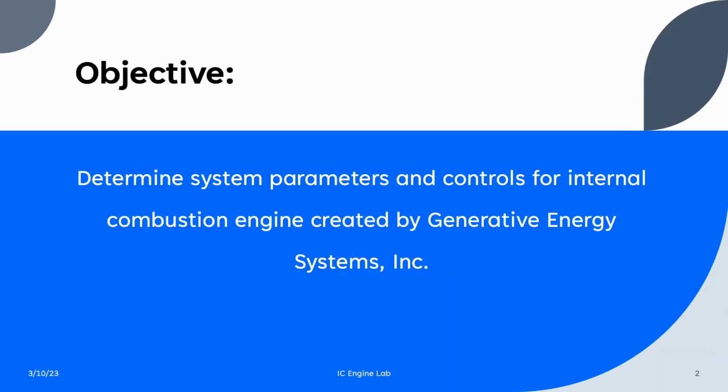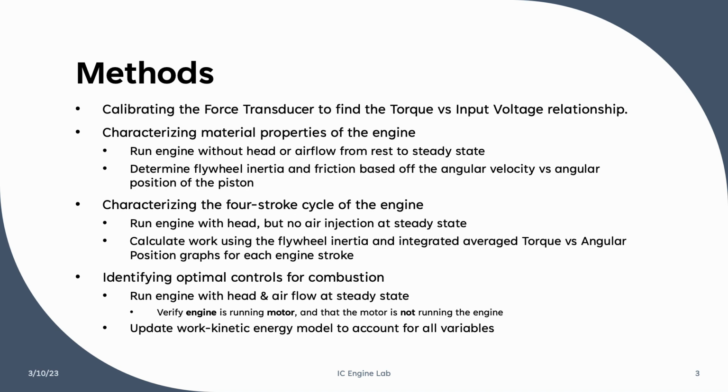The objective for this lab was to determine system parameters and controls for an internal combustion engine that was created by Generative Energy Systems Incorporated. The methods for this lab include, for week 1, calibrating the force transducer to find the torque versus input voltage relationship,